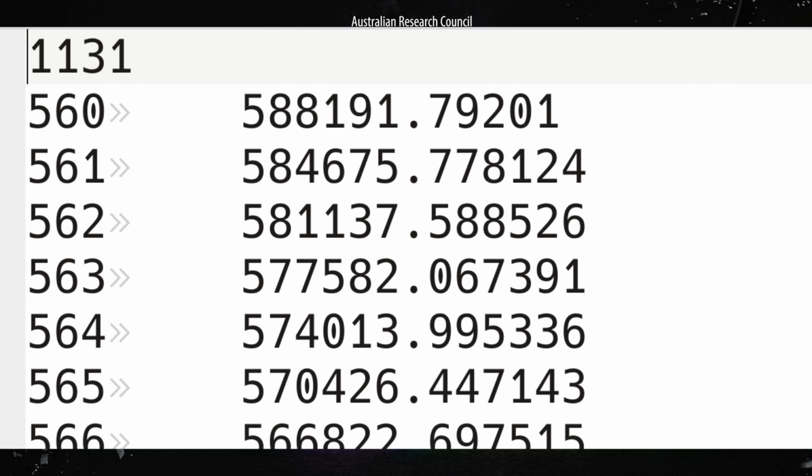In your data file, the first row gives the number of rows of data. The software is not smart enough to figure that out on its own. You need to tell it. From then on, the first column is the wavelength of the measurement, and the second column is the molar absorptivity. Go ahead and try it with the example file we've provided. The sensitizer absorption spectrum is of critical importance because it determines how much light is captured by your device, which limits how much light can be converted to useful work.